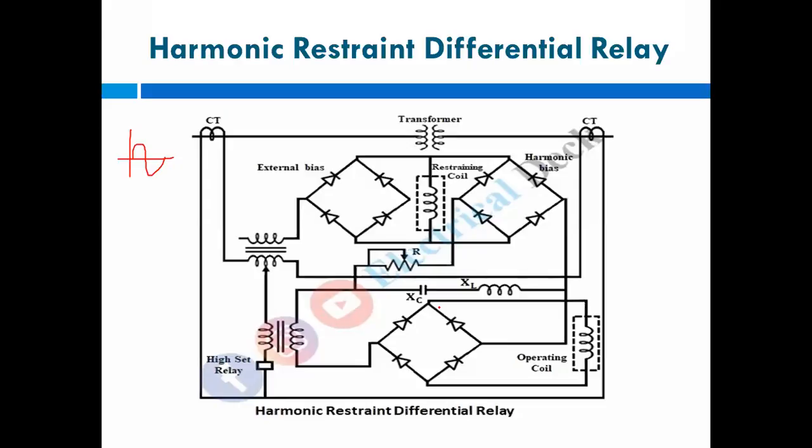There is a restraining coil also, but when this operating current becomes more, the restraining force becomes low, and your relay starts operating immediately.